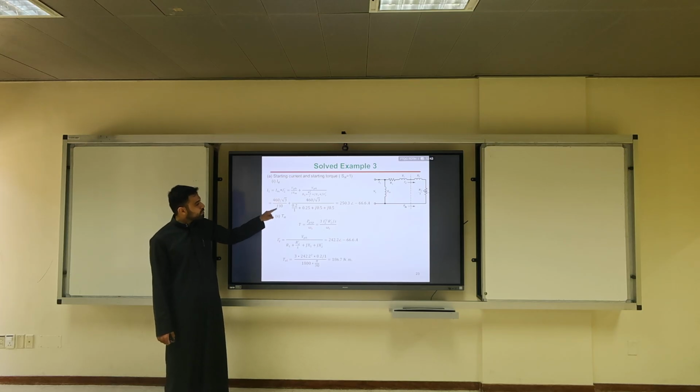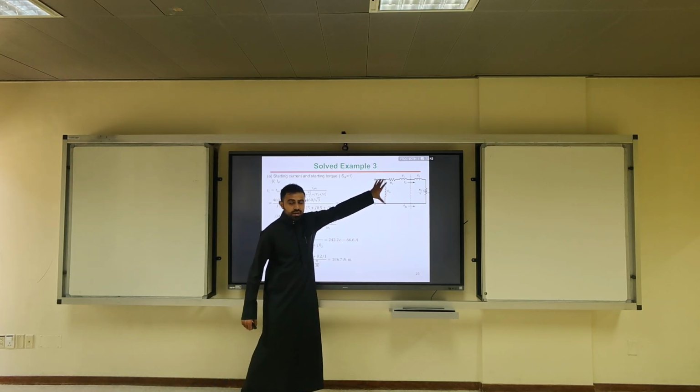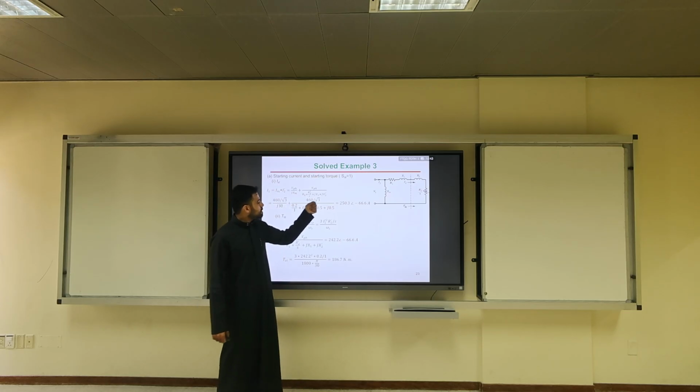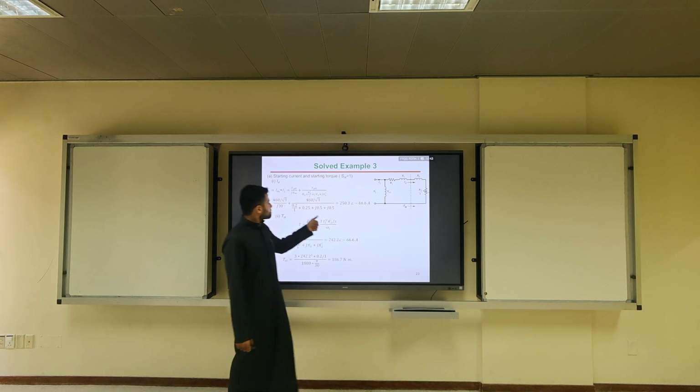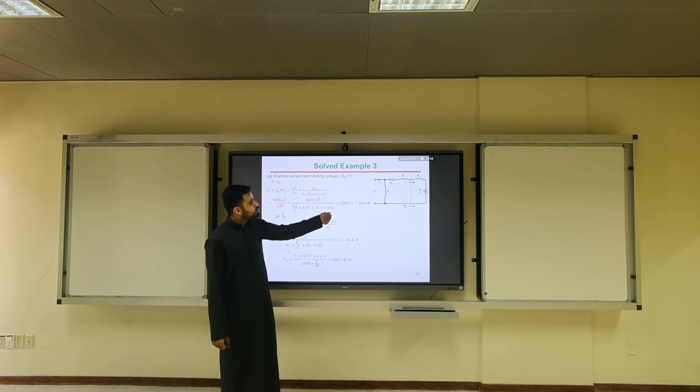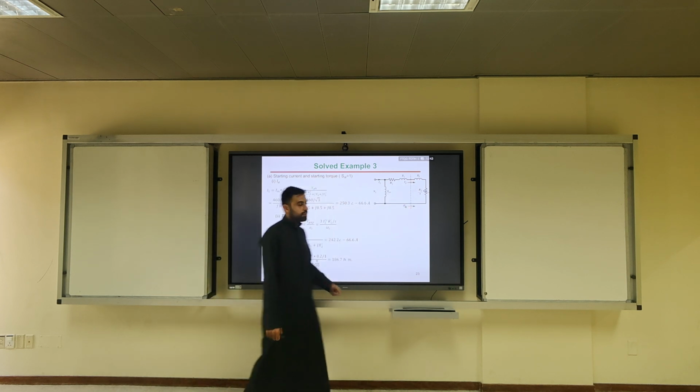It's 460 over square root of 3 divided by j30, plus 460 over square root of 3 over (0.2 over 1 plus R1 plus j0.5 plus j0.5). Why did I put 1 here? Because at starting torque, the slip equals 1. R2 prime over s, each reactance being j0.5.